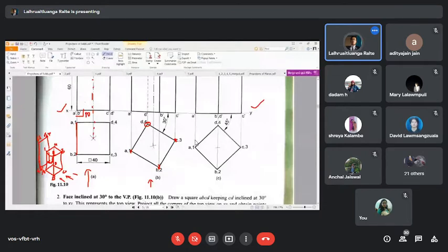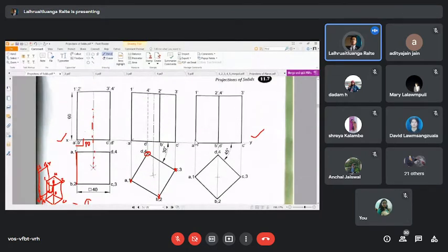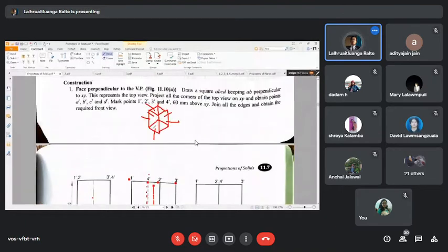So when we are drafting, when we are drawing the front view, we are going to have the 3 points A, B, and C from the base directly visible, 1, 2, and 3 from the top part directly visible, and D and 4 are behind us. This is why we still annotate them, but with dotted lines. All right, and we have the axis over here as well.